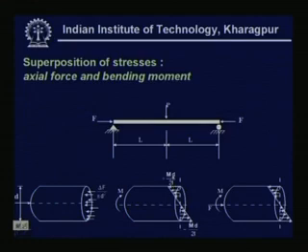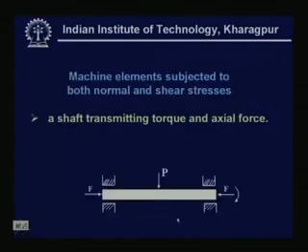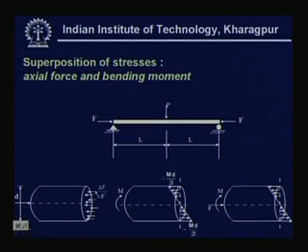My by I, where y is d by 2, and I is the moment of inertia over the neutral axis. So, this is the bending stress distribution. You can see a uniform distribution, these two magnitudes are the same, and this magnitude is superimposed.